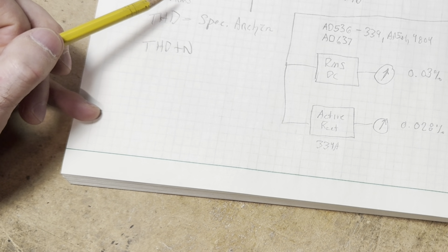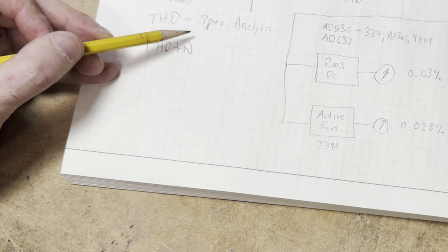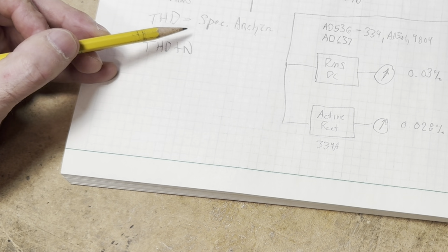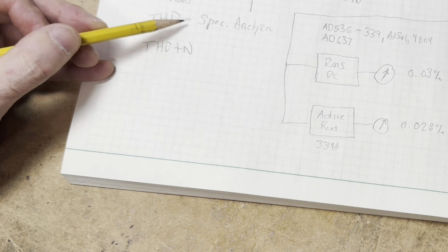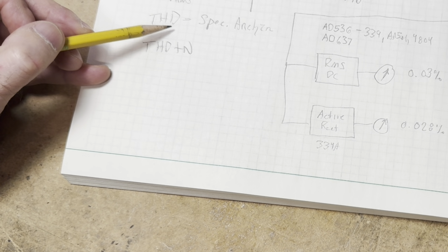We do add those numbers together to come up with some value, say arbitrarily set minus 75 dB. I know that's not correct, but just for the example here, then we would say that the sum of our harmonic components is minus 75 dB below the fundamental. That will be a measurement of total harmonic distortion. We're looking at the distortion with respect to harmonic components.